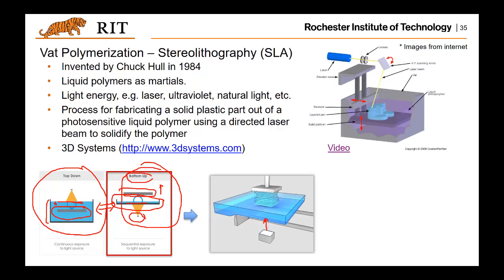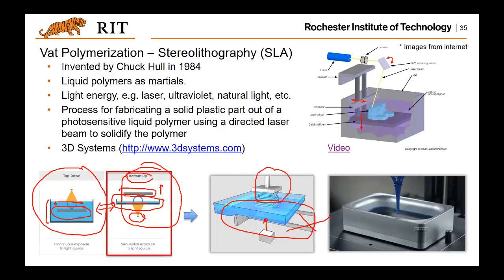Understand it? And if you take a look at this illustration again, you will realize the building time for this process relies on this lifting as well as this separation motion. So you might ask if there is any way to reduce the building time, because if there's a way to prevent the sticking of the part to the bottom of the tank, then we do not need this kind of separation motion. So there are some newly invented processes like the one shown here. This is the continuous liquid... I don't quite remember the full name, but it's a continuous motion.